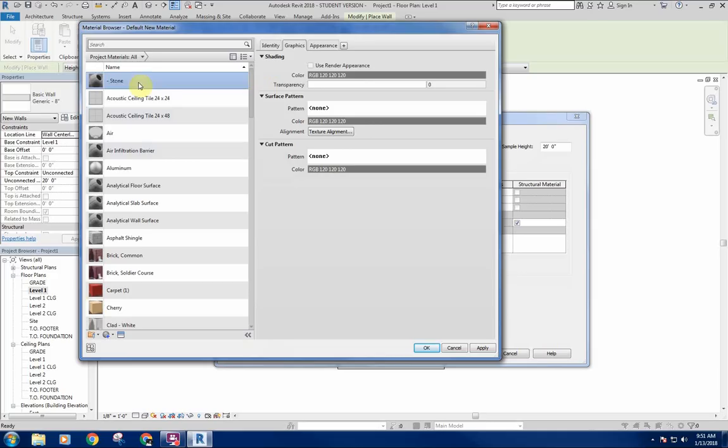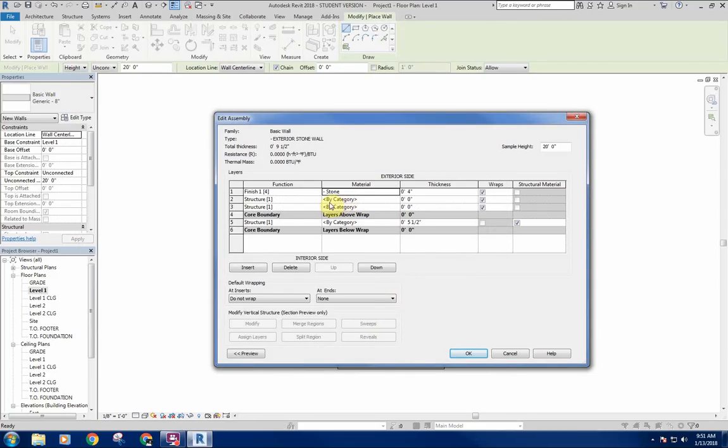And I put the dash so it sorts it to the very top, just like the walls. I'm not going to get into the appearance or anything like that yet. I'll deal with that later, but for now, as I'm building the wall, at least I've got my stone texture applied there. Then I'm going to end up with an air layer. We'll make that an inch. We're probably going to end up with a 12-inch thick foundation to support all of this. Let's add our 1/2-inch drywall on the inside down here, and we'll say that's finished too.